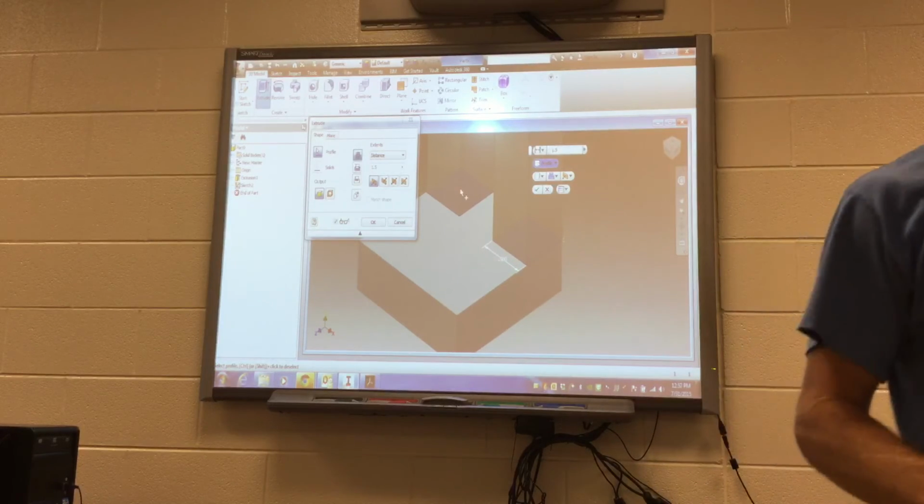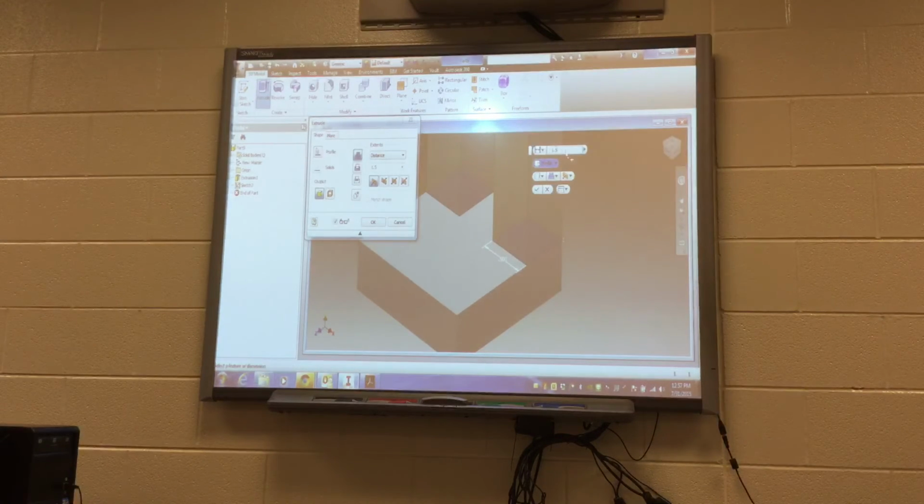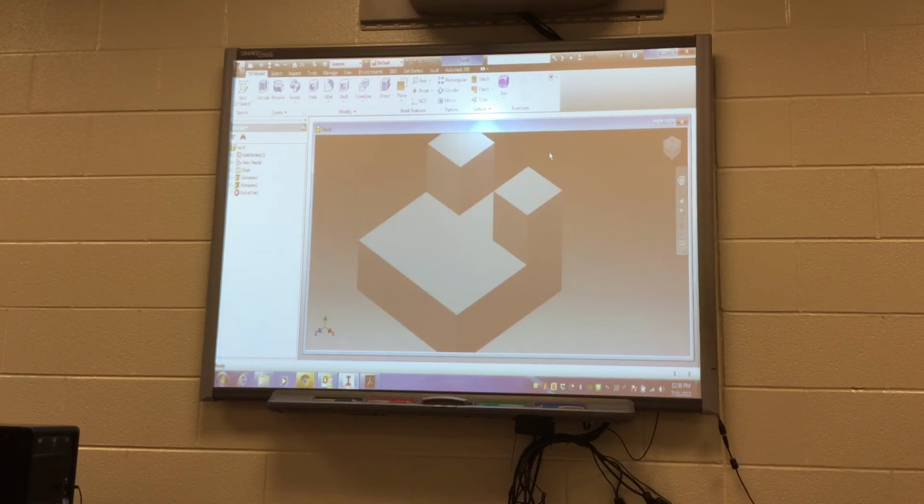Okay. Then make sure you change your sketches or your dimension and hit enter. And that's basically that shape by adding things on. Okay? Questions with that one? That's how you add things onto the shapes, and you can keep repeating that process over and over and over again. Now notice, in your browser, there's two extrusions now.